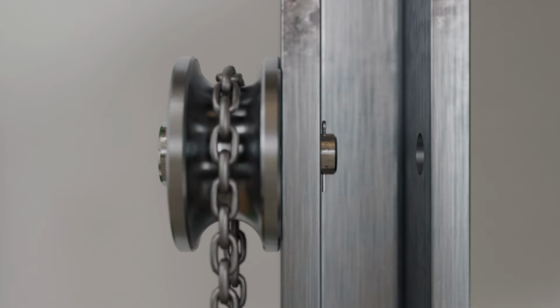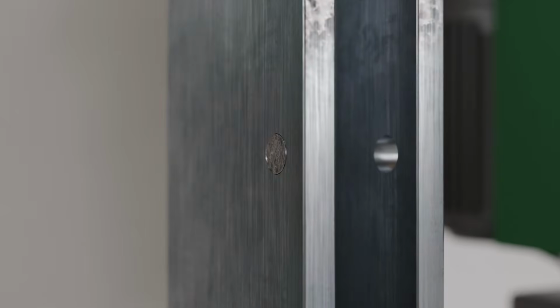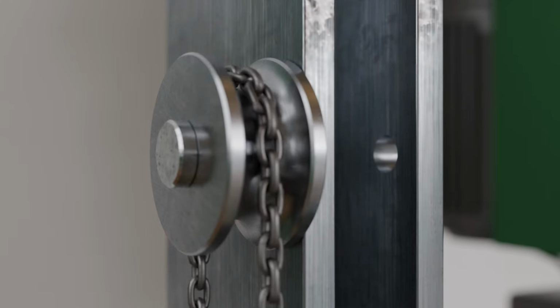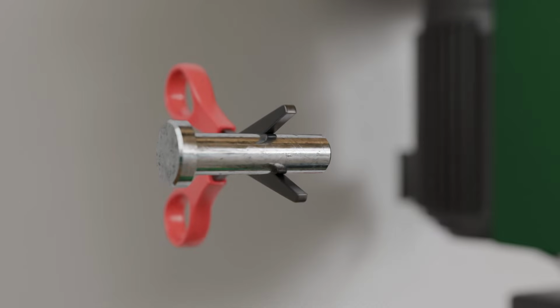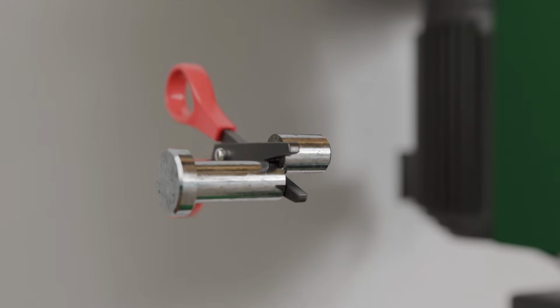The bolt is subjected to shear loading in the cross-section between the pulley and the support. If the force in the chain becomes too large, the bolt would be sheared off at this location. This shear loading can indeed be compared to the action of the two blades of a pair of scissors. Just as a sheet of paper is cut between the two blades, the bolt is cut by the pulley and the support.